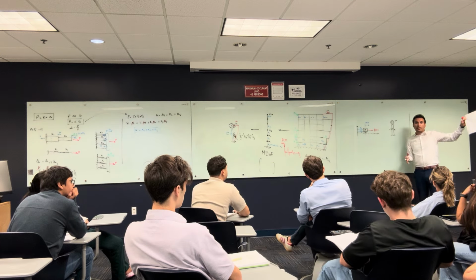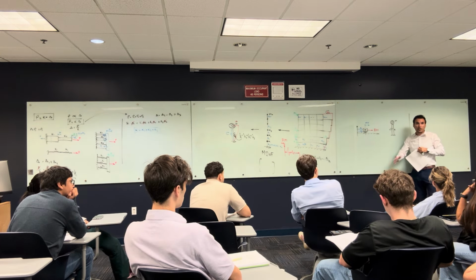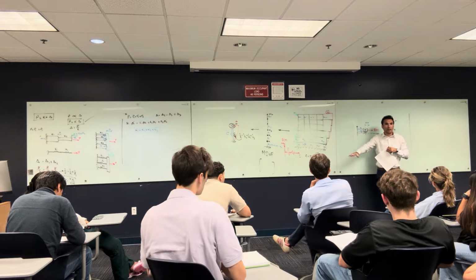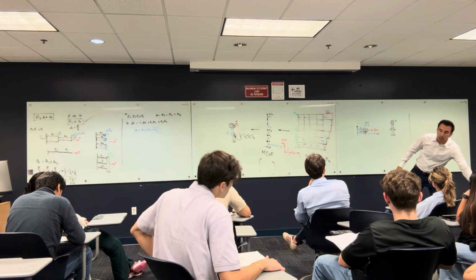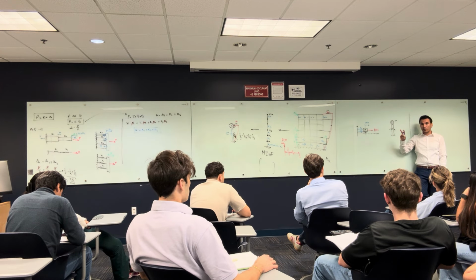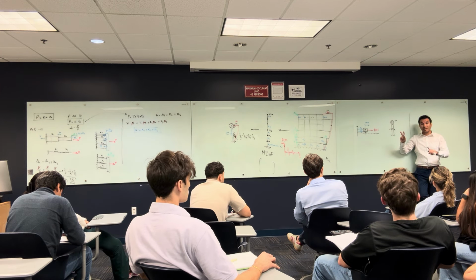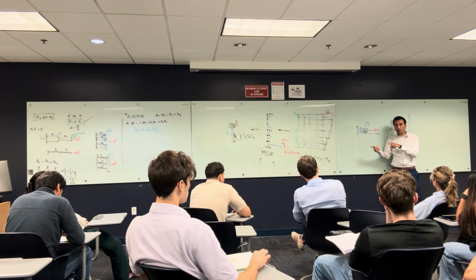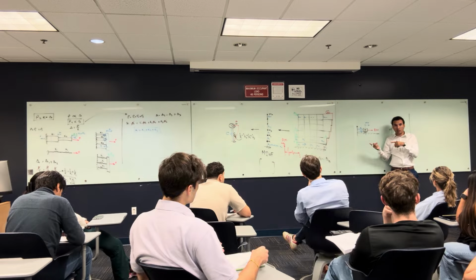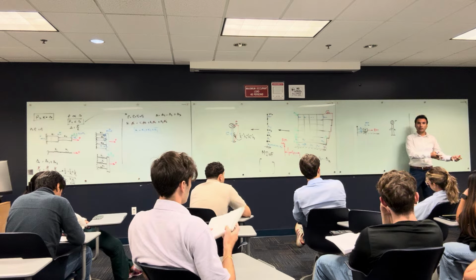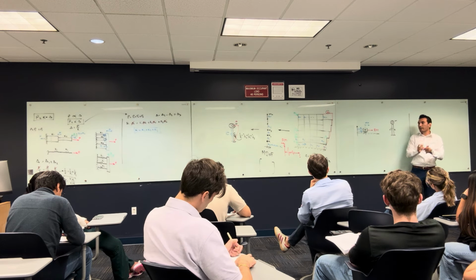Like if something happened in LA, nothing's gonna happen here, right? Because the whole thing is getting dissipated in the soil. But let's say in the same region, they all are gonna have the same ground acceleration. So I want you to differentiate between two accelerations here because this is really, really important: the acceleration of the earthquake and the acceleration of the structure. And what happened first? The earthquake or the structure? The earthquake has to happen first, so my structure can have an acceleration.